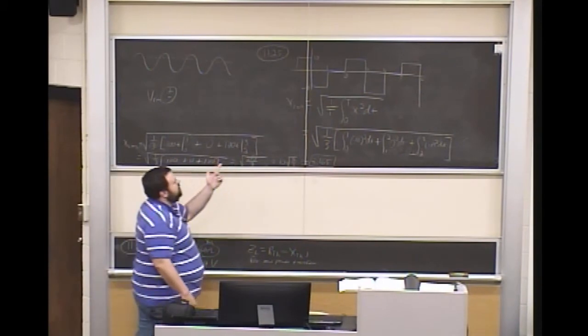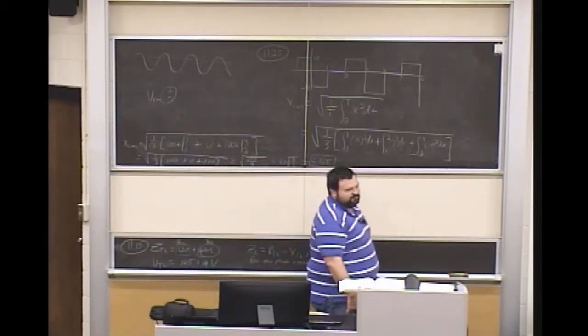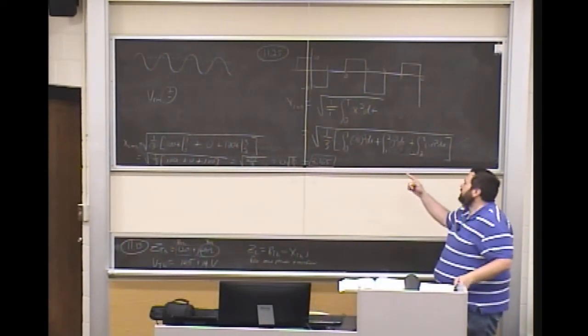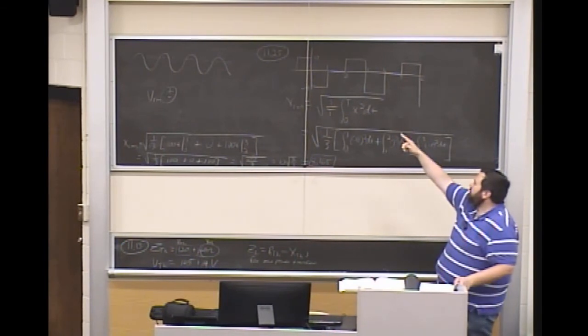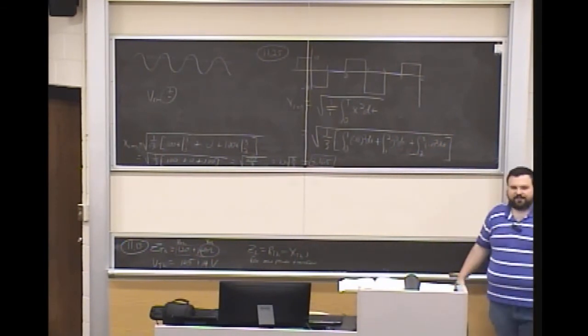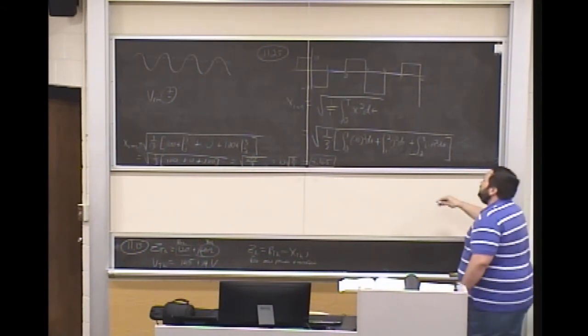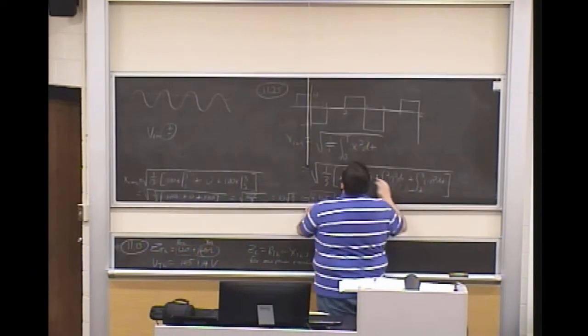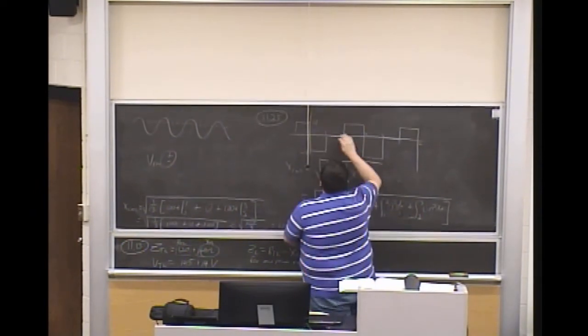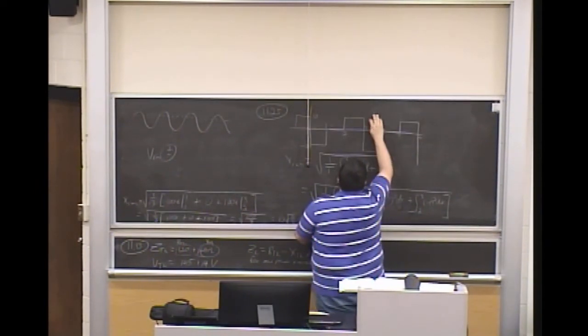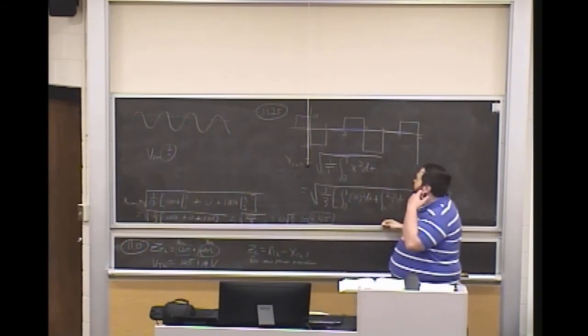Yeah, and really, we could have just done this completely graphically, but to get the RMS, it's not analyzing the integral of this graph, it's analyzing the integral of the square of that graph. So we could have just redrawn it as the square, in which case each of these would go up to positive 100, positive 100, things like that.